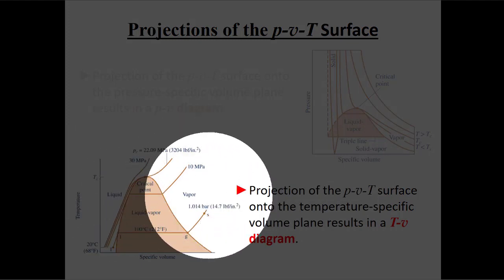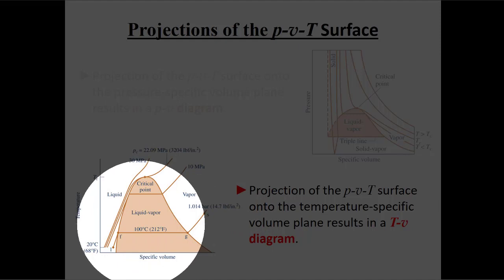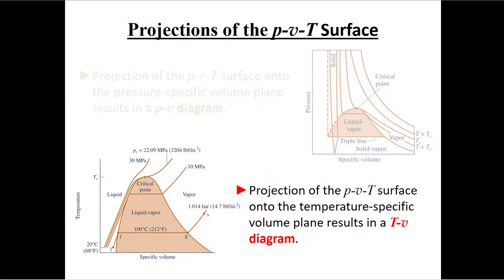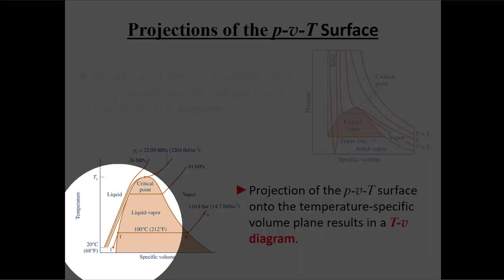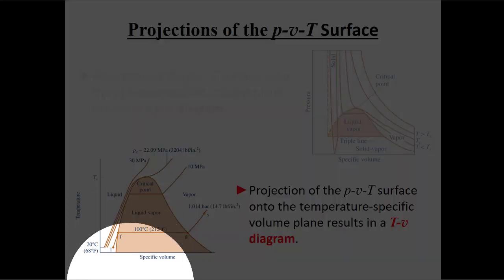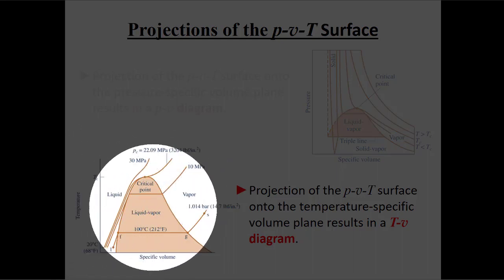Anytime I'm on the right-hand side, I have vapor. And anytime I'm underneath the vapor dome, then I have some combination of liquid and vapor. So what's interesting here too is we have some constant pressure lines, right? Because we know that we're interested in P and V and T and V, right? So I have constant temperature lines, which are any horizontal line on this graph.